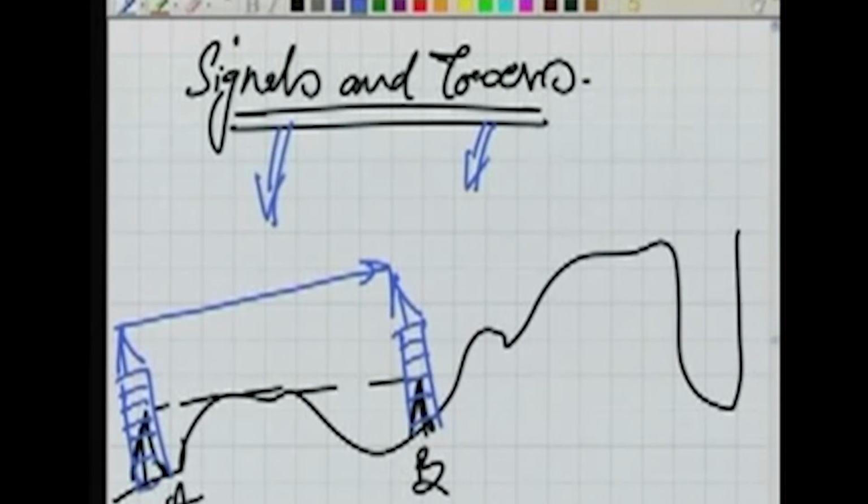Now the signals, all this material is given in any textbook. So please go through any textbook on triangulation and you will find a lot of running material which talks about the signals. Signals could be like the ranging rod. We have seen the ranging rod. The sunlight gets reflected and then it works as a signal. Similarly, we can have a thicker ranging rod, a wooden cylinder, painted white and black or red and white, and we are using that as a signal, something to bisect.